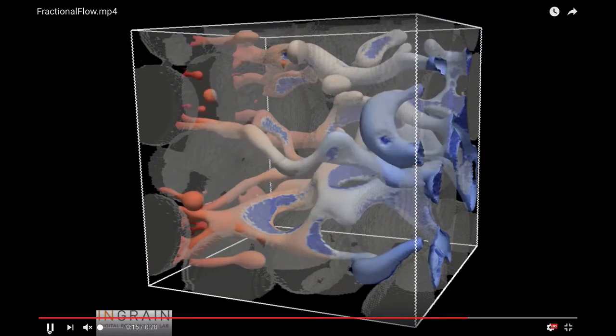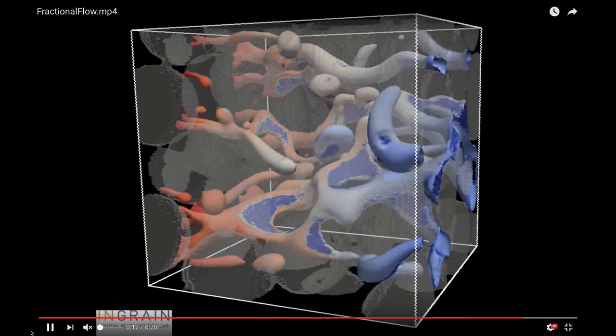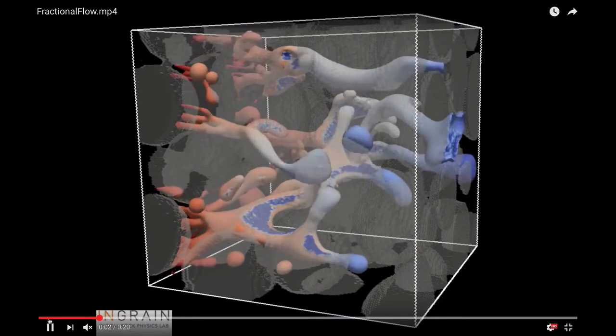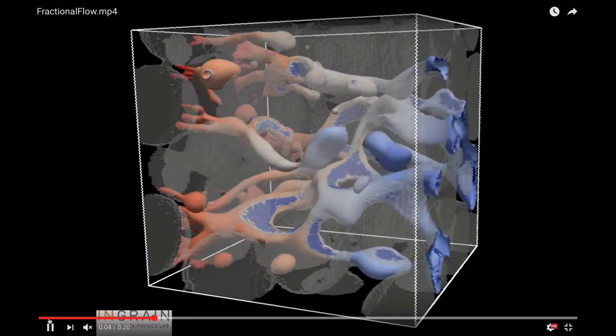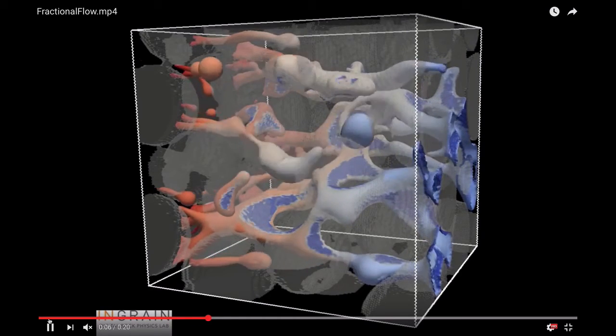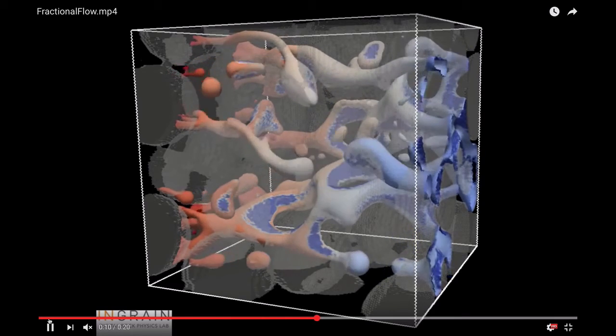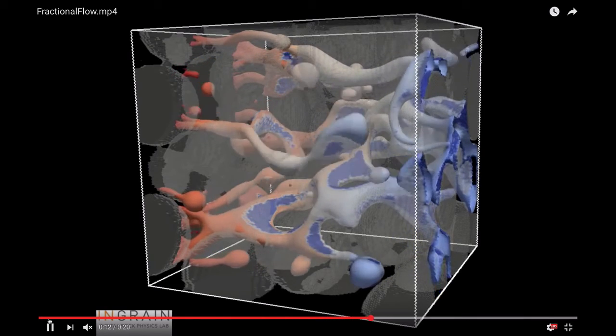And so you can throw it away. You can make calculations in porous media flows by throwing away this momentum term, which means that the momentum equations you would have to solve and honor, you can throw away as well, and you just have to solve conservation of mass.